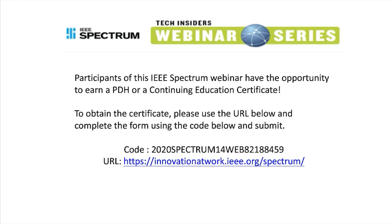Okay, great. Let's go to the next question. Up to what bandwidth does the DPD algorithm work? Yeah, the performance of the DPD algorithm that we have depends on the algorithm specification. The one that I showed you in this slide definitely works up to 50 megahertz. That is the first bandwidth of the 5G.